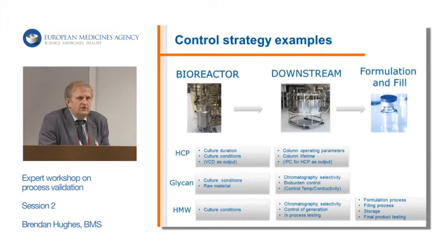And so if you think about guaranteeing yourself that every batch you make of a product will have an acceptable limit of high molecular weight, we need to have understood the conditions that evolve and remove that material in the process, and have the right kind of control strategy so that by looking at the data, and I'll talk a little bit about the systems we're beginning to leverage for that, you can look at a data set coming off a process almost in real time, preferably in real time, to understand the level of control you have is going to deliver a product with the right characteristics.